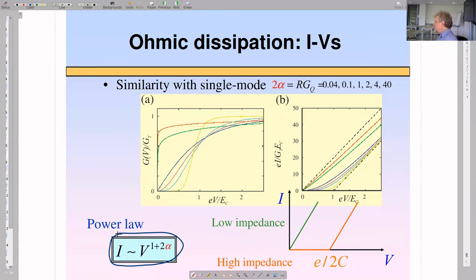The current-voltage curve of a tunnel junction, at least at zero temperature, is not linear in the presence of any environment. It also requires this anomalous exponent, and basically, it's always smaller than 1. One can see it from the plots of differential conductance.